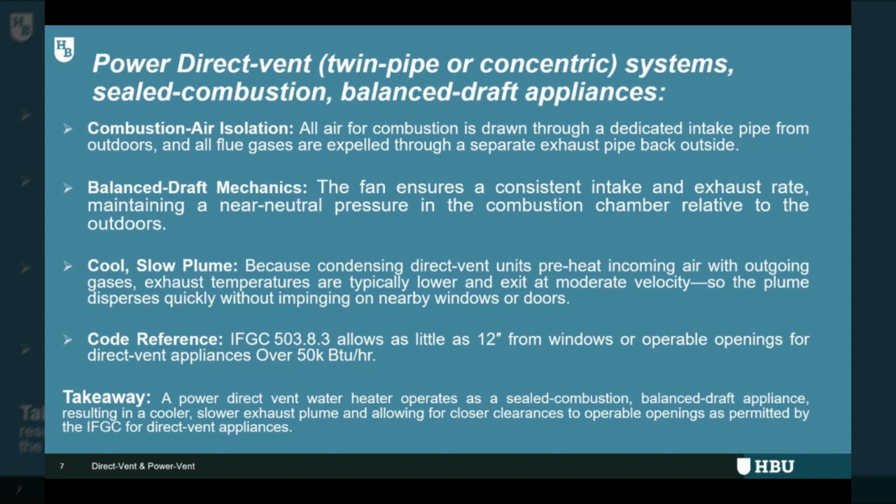The key is that they are sealed combustion balanced draft appliances. First, combustion air isolation. These systems are completely sealed off from your home's air. They have a dedicated intake pipe that brings in 100% of the air needed for combustion from the outdoors, and a separate exhaust pipe that sends all the flue gases right back outside. This means no combustion byproducts can leak into your home's living space.